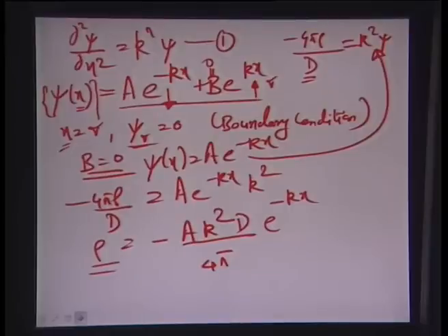The only factor that I would like to mention here is that the basis of this density of charge would be the dependency on the surface of a particular electrode. In case of electrokinetic microchannel flows, if the surface is silicon, there would be a certain bond density, and there would be a huge number of silanol bonds on the top of the surface, which would give it a negative charge, SiO minus kind of moieties, as it is exposed to a solution of a certain pH. So, if this kind of treatment is given on the surface, there is a tendency of the fluid to develop a diffuse layer of positive charge, or a counter ion cloud of positive charges, and therefore, the surface charge density would be a function of how many active sites there are on the surface which can get silanized, which can get converted into SiO minus. Okay.